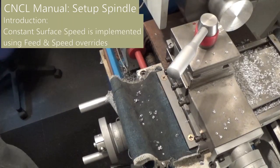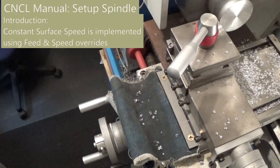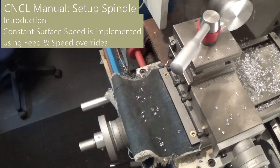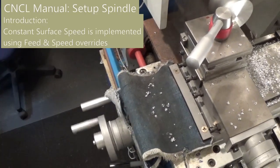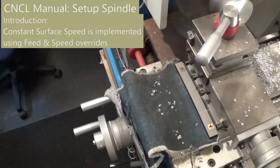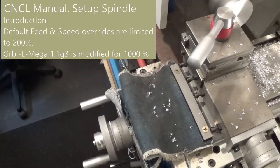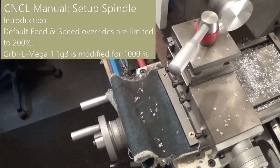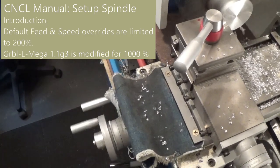Grbl doesn't support G96 G-codes for constant surface speed. Therefore, constant surface speed is implemented using feed and speed overrides. As you can see, it is working pretty well. Most Grbl controllers have a 200% override limit. I modified Grbl L Mega to accept a 1000% override limit.